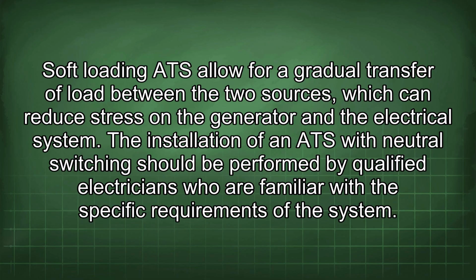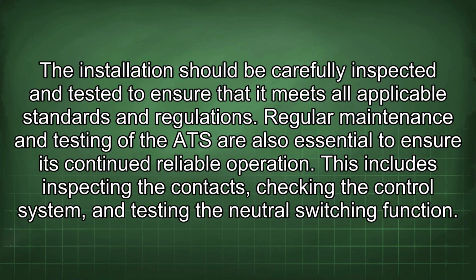The installation of an ATS with neutral switching should be performed by qualified electricians who are familiar with the specific requirements of the system. The installation should be carefully inspected and tested to ensure that it meets all applicable standards and regulations. Regular maintenance and testing of the ATS are also essential to ensure its continued reliable operation. This includes inspecting the contacts, checking the control system, and testing the neutral switching function.